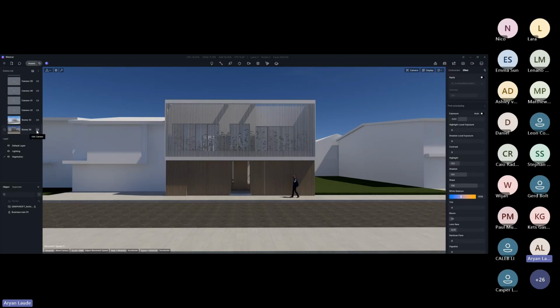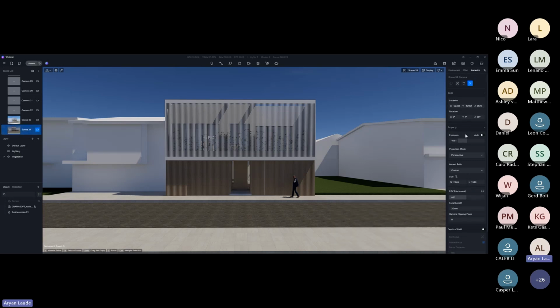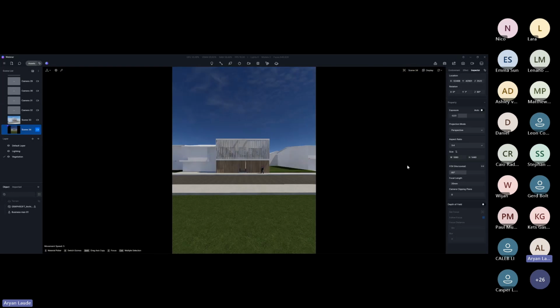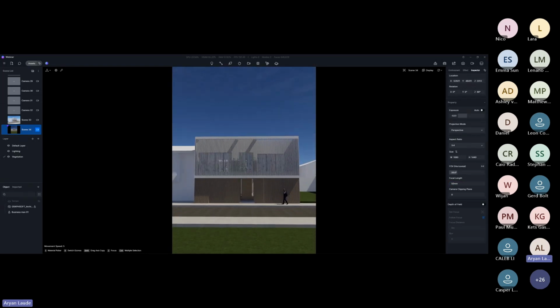and toggle in the edit camera. Selecting the edit camera will allow us to open the inspector tab, wherein we can adjust multiple parameters as well. I wanted to create a 3:4 aspect ratio, so I can select the aspect ratio tab and go over to 3:4, and it will create black bars. Adjust my focal length to 50 millimeters, and turn on the 2-point perspective mode, which is F8 or P. Since I have already created my camera position, all I need to do now is update my scene, and I already got this set up.